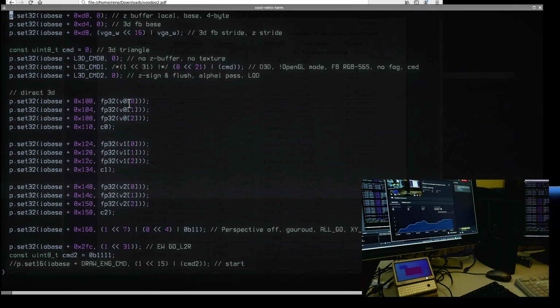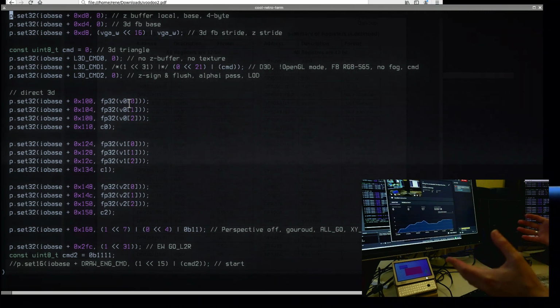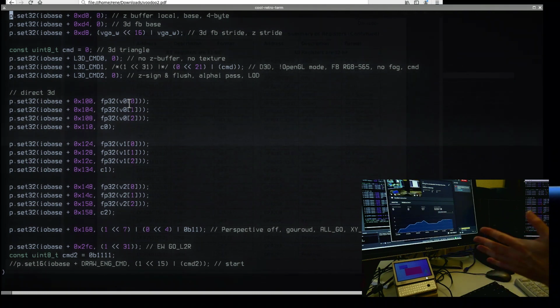And you can do this even more optimized. So normally you would use direct memory access for this. The hardware can do this. For this we would need to pin one memory page in memory, and the format is not very well documented. However, I have not implemented DMA on either the Voodoo or the Verge. For very high performance you could do this, but so far I'm already happy that this works. And next are of course textures.